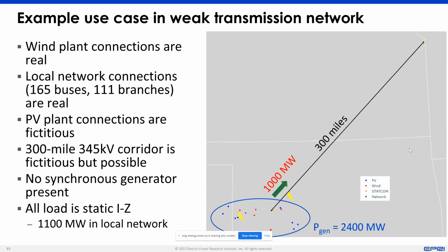And you may not need frequency control on this end. In this case, we didn't have any frequency control on the resources here, so all the frequency response is being provided only from here. There is another set of research work we have been doing to showcase that it does matter where you put frequency control also, because depending upon where you put it, you can have stable or unstable responses, especially with fast frequency control.